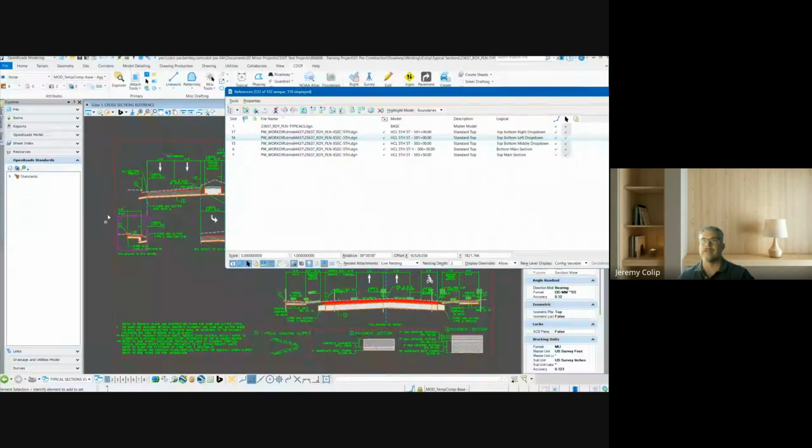Well, on my end conditions, if I have a separate end condition that I want to show, okay, it's going to do this from here to here, but my roadway width is going to stay the same, the striping is going to stay the same, then I can go ahead and pull that drop down in. All I'm doing is clipping that drop down and showing what I want to show for that end condition. So again, if my design and my model changes, my cross sections change, my typical changes, all from one unified data source, which is my design model.